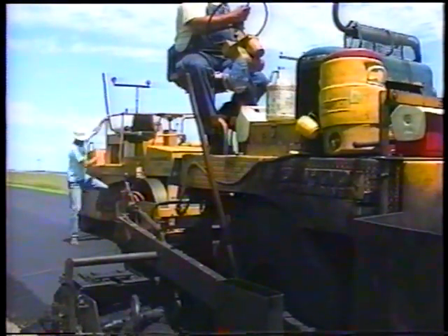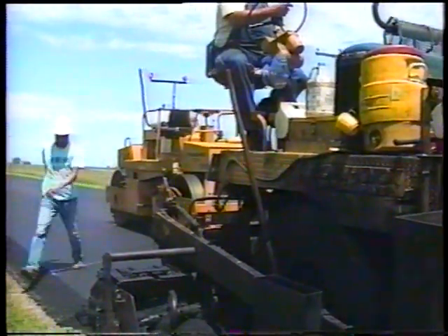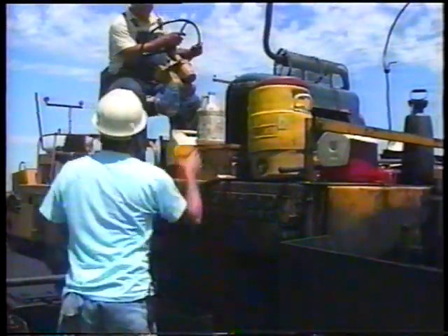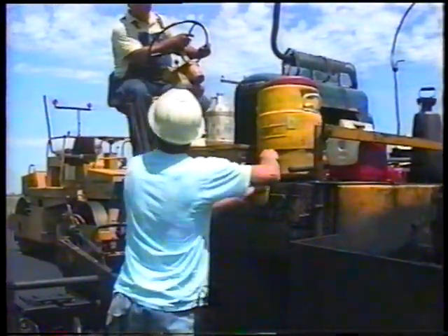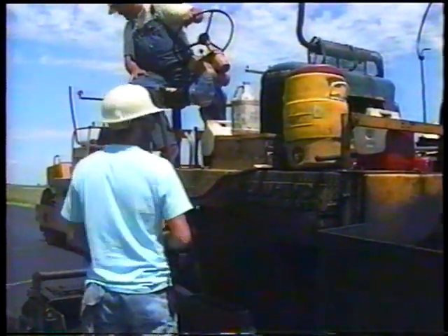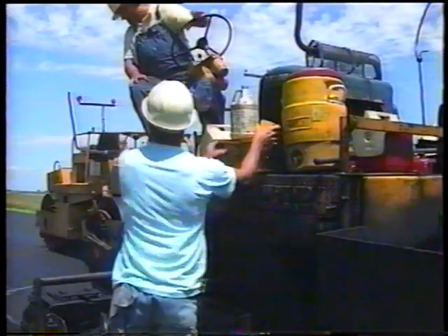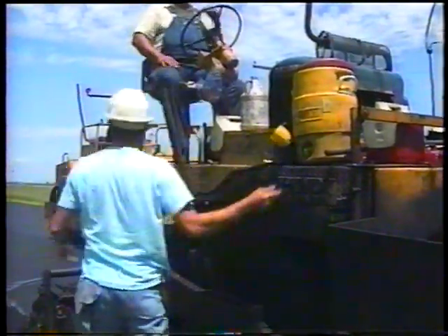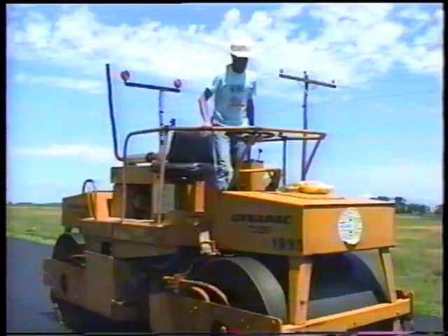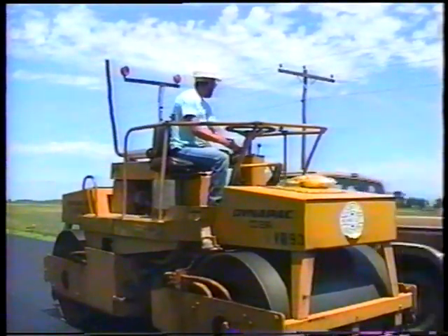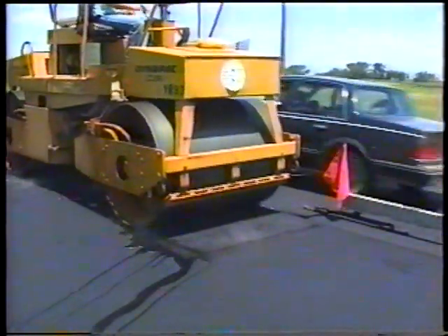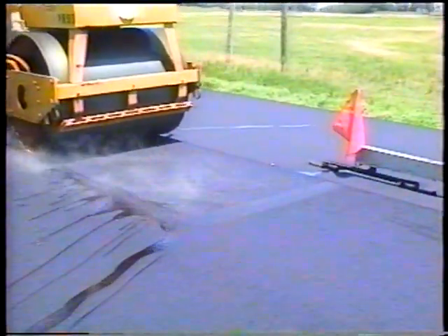Some people call this hot mix. Some people call it hot asphalt. You can call it hot for short because it sure is, especially in the middle of summer. A nice cool drink is not just a luxury, it's a requirement. But never park the roller on the fresh mat, especially right behind the paver. The weight of the roller depresses the mat, causing a bird bath. And fortunately for the crows, and unfortunately for you, it can't be rolled out.